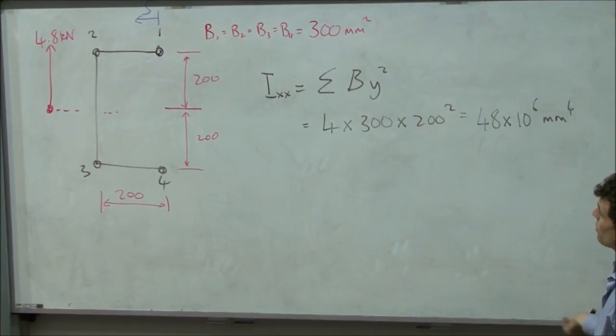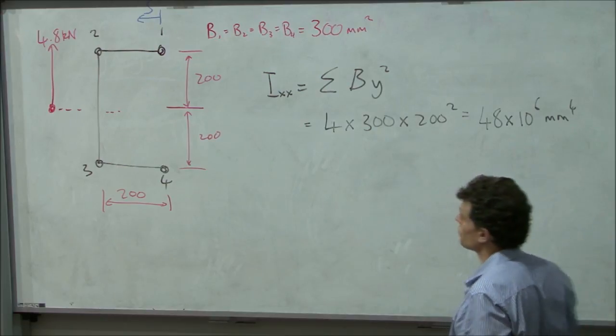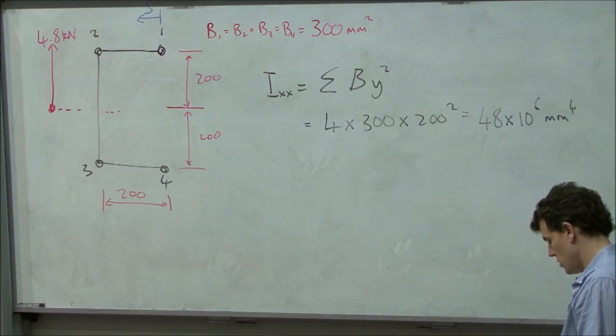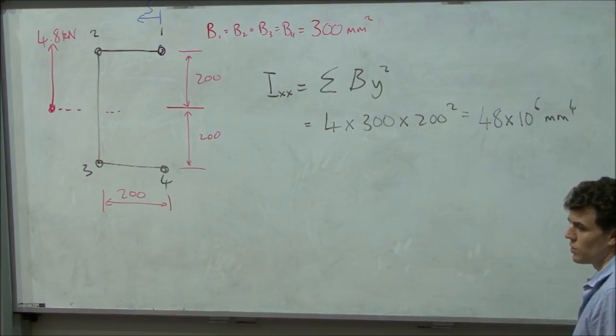So in all of these calculations, IXX is the first thing you've got to do. Or find the centroid. If it's not symmetric, you have to find the centroid, but it's not common that I'll give you a non-symmetric problem.